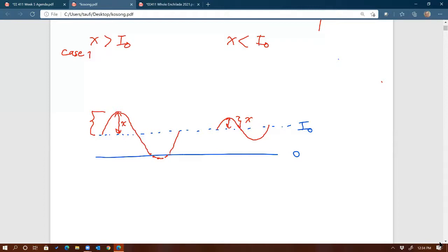Yes? Okay. Just a quick question, for my own clarification. You're saying, Professor, that the peak has to be greater so that it can touch 0, because if it's less, then it won't hit 0 and it'll just keep going sinusoidally, right? Correct. Exactly. And that's the key for zero current, right? We want to deliberately have the sine wave hit 0 and try to go negative, because we have the unidirectional switch, we clamp that current to 0. So this is the perfect time for us to turn the switch off if it hits 0 and stays at 0. Whereas if you have case number 2, where the offset is larger than the peak of the sine wave, then this sine wave will never reach 0, so therefore you would never get ZCS.